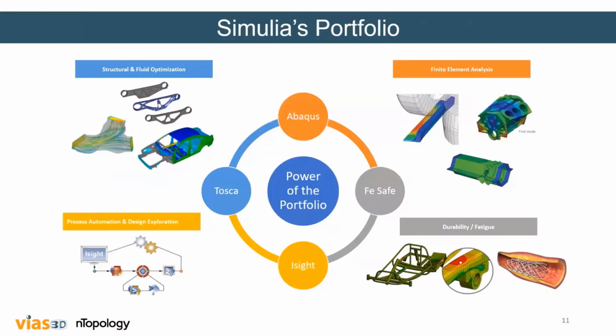It does the fatigue life calculation. It takes the stress or strain values from Abaqus or any other software where you can run the FEA, and using those stress strain values in the model, it does the fatigue assessment, fatigue damage assessment or fatigue life assessment. There are material properties also built into Fe-safe, which is more on the metallic side. If you have a rubber-like material, then the mechanism with which the fatigue is driven is different than in a metallic material. So there is another software solution available for that, which comes as an add-on with Fe-safe.